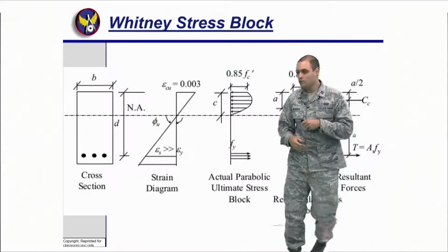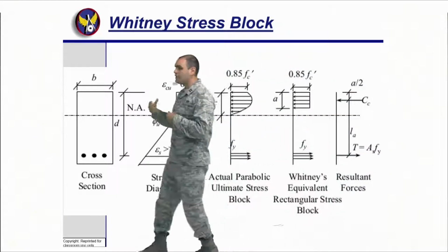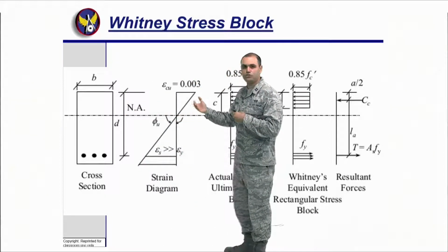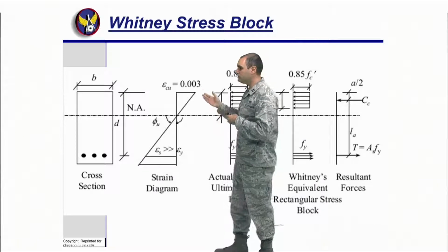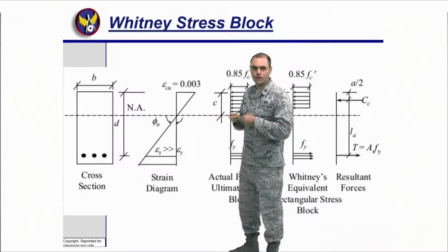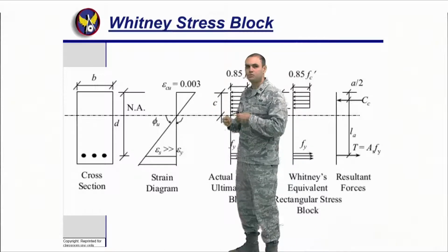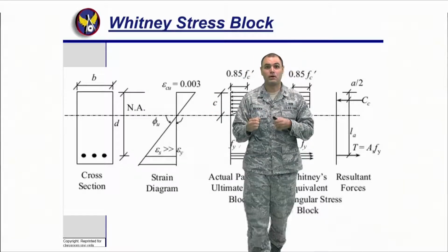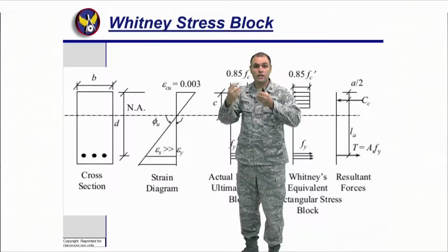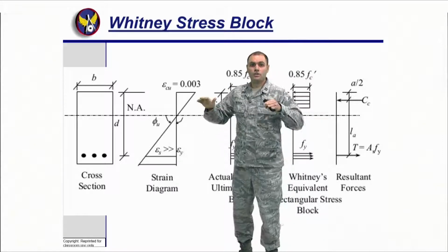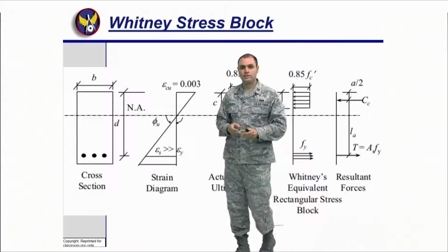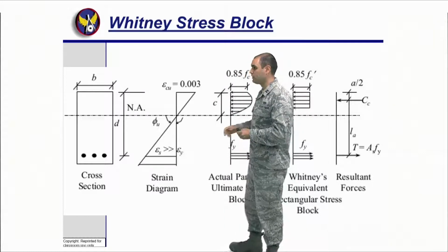All right. So what is going on, right? I talk about the neutral axis, and here you see it. You see first off the strain diagram, and you get to see that I have the strain for concrete, the ultimate strain of concrete, which we're going to call 0.003. That's a really, really small number, right? Why do we have to use really small numbers? Because again, think about serviceability. Would you like to work in a building where every time you walk, you start jumping up and down? No. And I'll explain that a little bit better when you guys and gals actually come out here for 481.